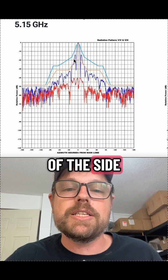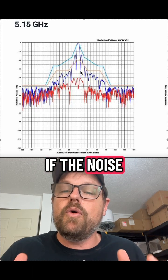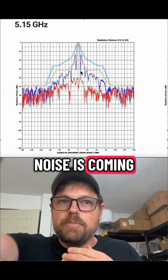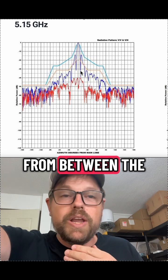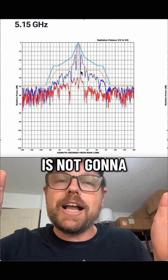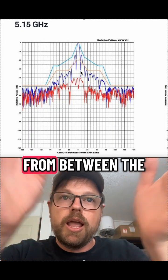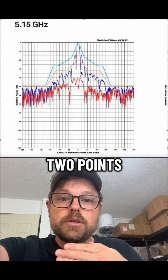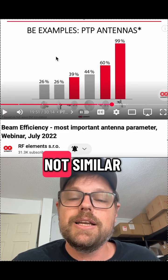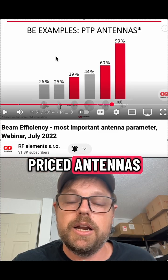By moving some of the side lobes into the main lobe, that may help if the noise is co-located. But if the noise is coming from between the two links, then having that wider beam width is not going to help at all. In fact, you could be picking up more noise from between the two points. Keep that in mind too. So the comparison is not similar gain antennas. The comparison really is similar priced antennas.